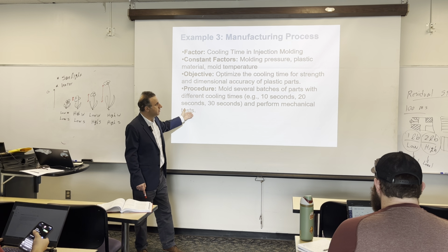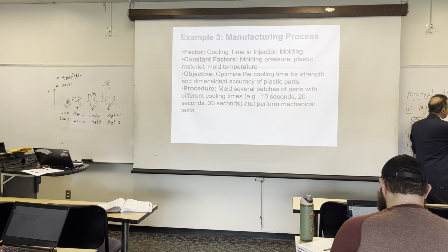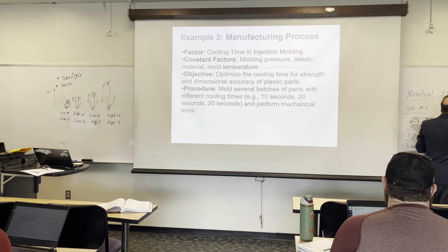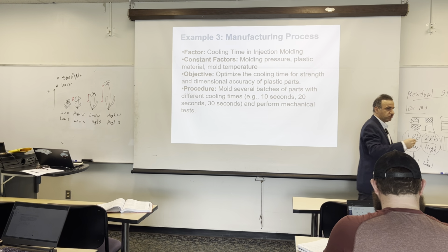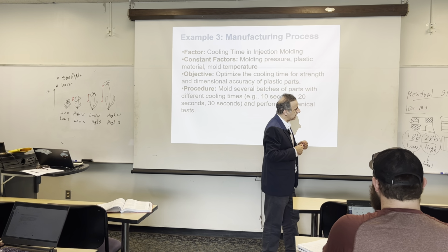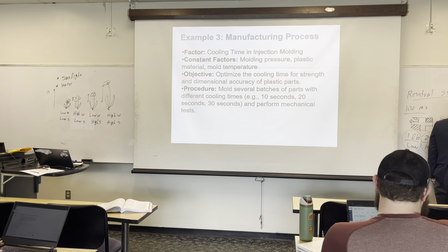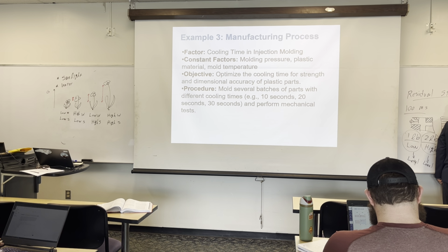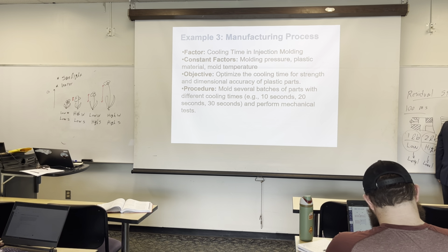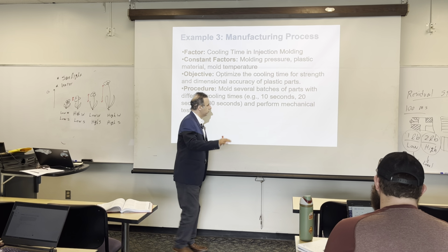So the output here can be anything from this experiment: the strength, modulus, yield strength, also ductility, right? Elongation. Another thing that we can get from here is called toughness. Measuring this, the area under the curve is called toughness. So these are all the information that we can get from simple tensile testing. We may have other mechanical tests, but this one is very general.